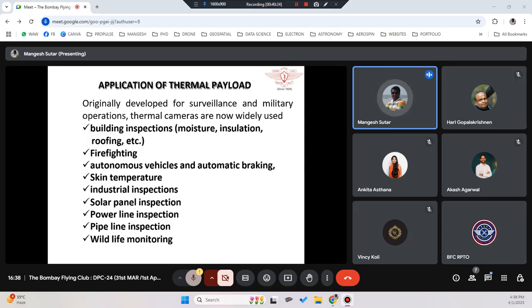Internally you can't do much about it unless you have some kind of protection initially, but over the period of usage of water pipelines, your pipelines get damaged from the inside. So you will not see a lot of damage from the outside of the pipeline, but inside the pipeline it would be happening because of the corrosive effect of the water. Those were detected only by the thermal cameras, because you see the difference in temperature. When we started taking the variation of the images on the thermal side of those pipes, we came to know there are some places where we are seeing spots.